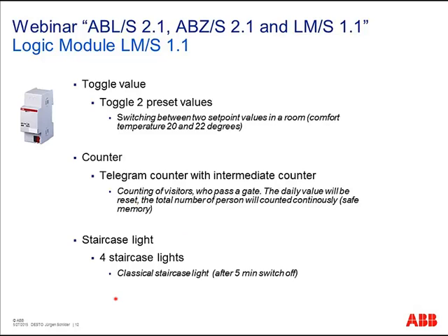And last but not least, a classical staircase lighting function. So you switch on a light, and after a certain time, adjustable, of course, light will be switched off. Also, I think well known from the switch actuator. So let's summarize. Some functions are very well known from other components, maybe not so often in use, but here also some special functions you do not find in other components and inside this logic module.